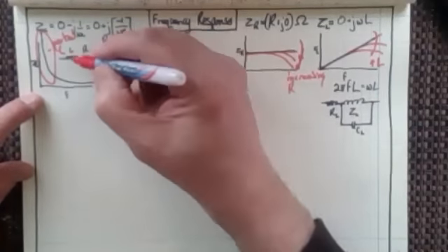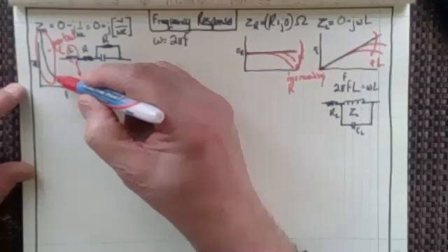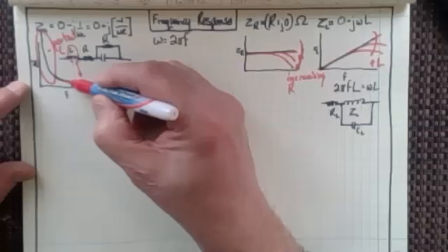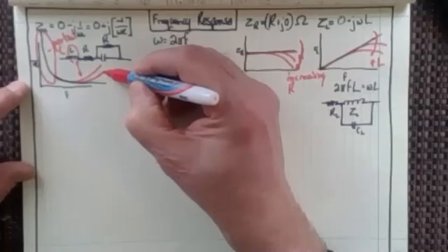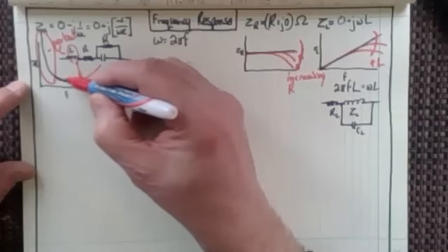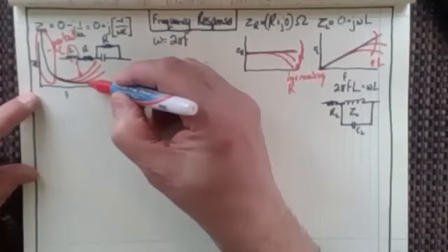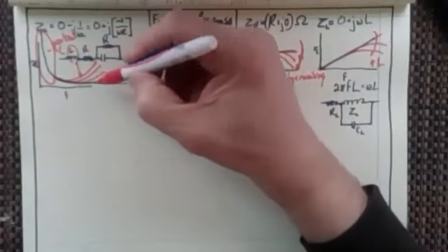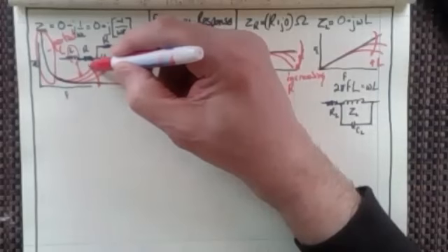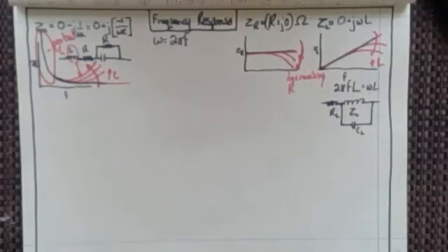Up here, we start to find that the inductive aspect of it starts to come into play. And so instead of having something like this at the very higher frequencies, we start to see the inductive loading come back, and we start to see the capacitor responding more like this than it is like this, right? Which is the way that it's supposed to. So with increasing capacitance, we're going to see that change in that way.